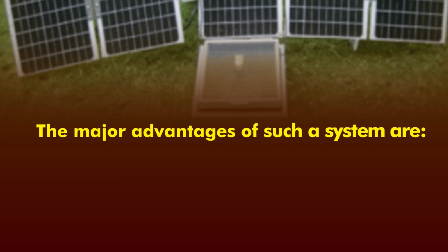It is a stationary system and can collect sun radiation throughout the day. The sun radiation falling from the top side is directly received by the absorber. The radiation received on the tilted cover is received by the absorber after reflection from the reflector. So, this type of solar cooker acts as a stationary concentrator.